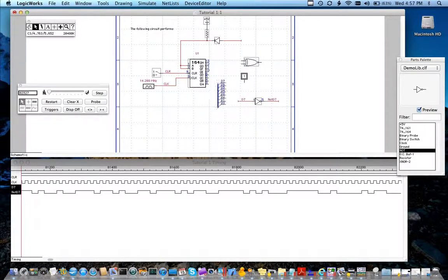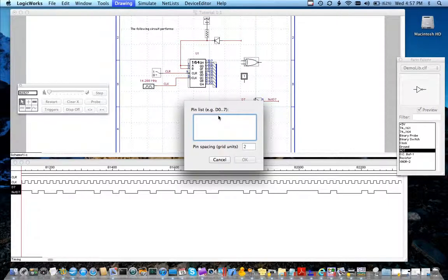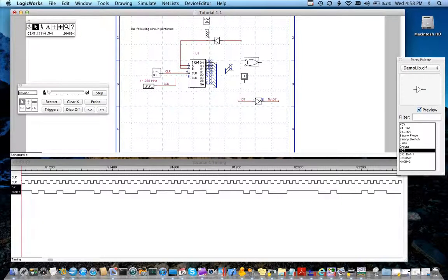Now the breakout happens to be pointing in the wrong way, so we use the arrow key to switch it around, and we butt it up right against there. Okay, and we terminate the placement mode by hitting the space bar. Now we'll create a couple other breakouts. The top one we'll create is D6.7, and we'll spin it around and we'll connect it there.